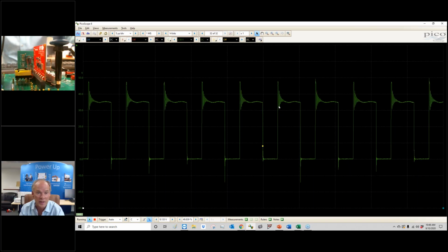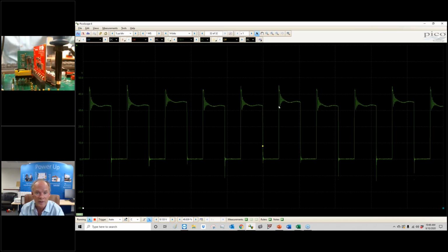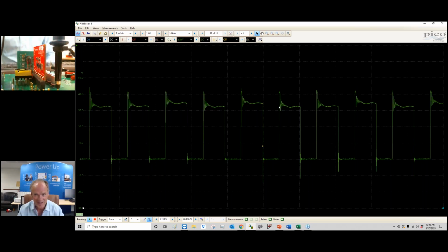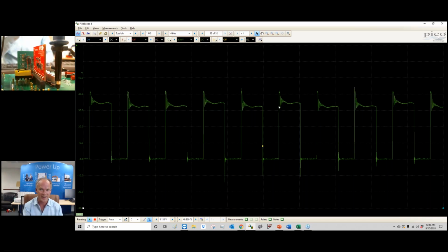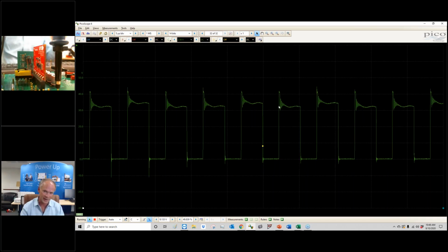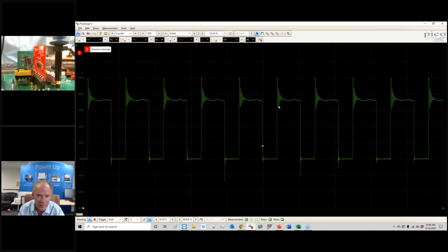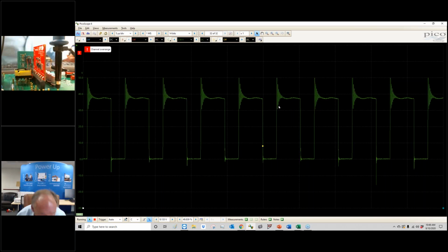Somebody asked a question actually on our group the other day, how do I stop a converter from hissing? Flyback converters from hissing? When it does this kind of thing, and there's that chaotic operation going on, the noise you hear is hissing. Even though it's switching at 200 kilohertz, there gets a low frequency component in there. You may hear that. I can hear a little bit of hissing in this one, but then when it cleans up, it goes away again.